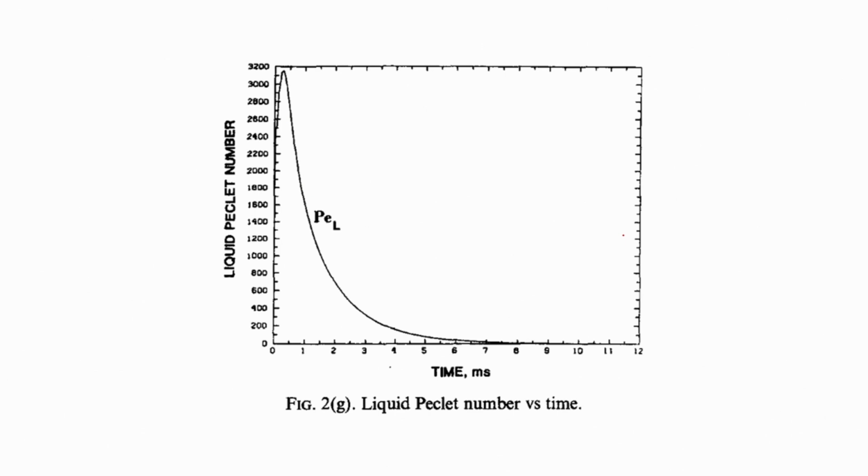Now, the other important part is the Peclet number. We used the vortex model mainly because of our Peclet number issue. We said that because the Peclet number is of the order of 100 and sometimes even more, sometimes of the order of 1000, we have to use the convection. That was the whole logic. And we also said that the Peclet number is the one that actually determines what kind of a mode of heat transfer one would have. Is it convection dominated or is it conduction dominated?